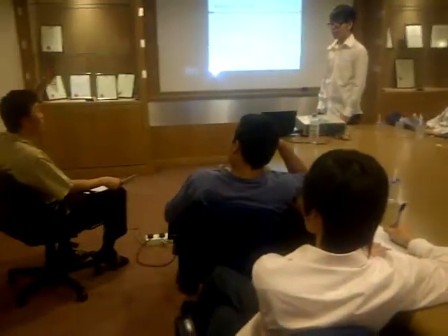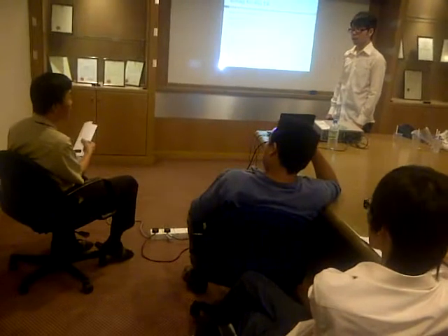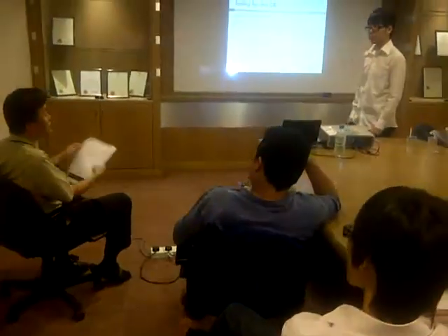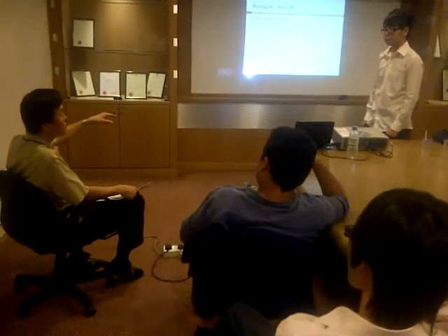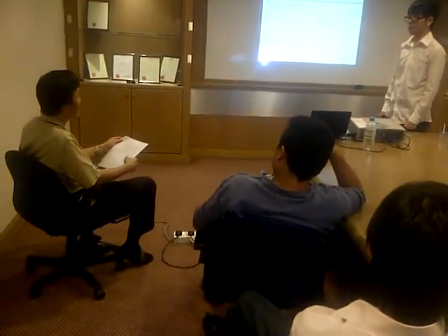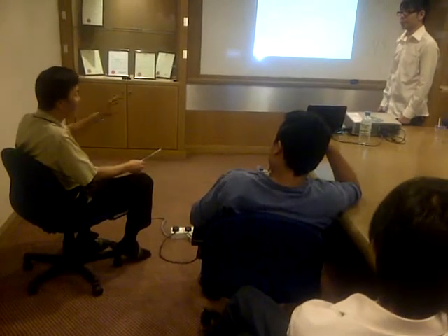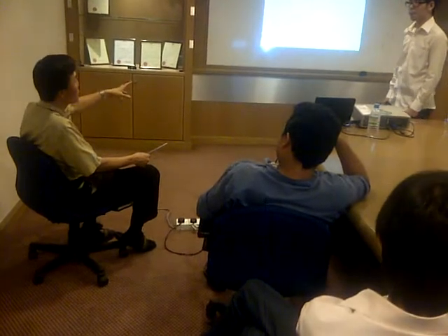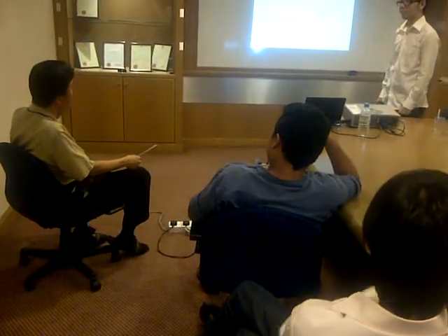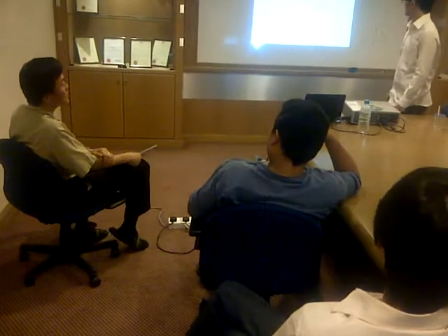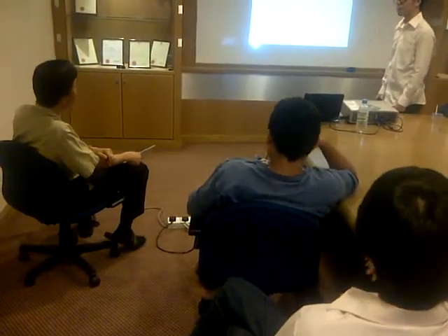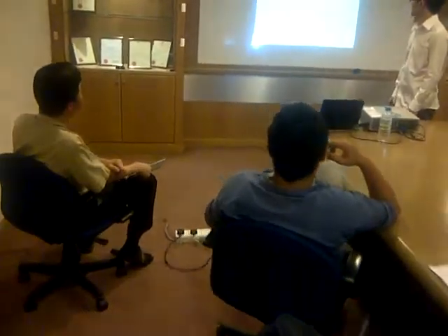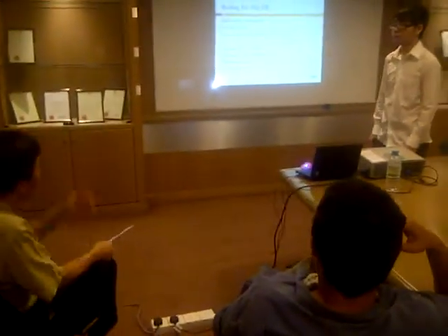You have to draft out the load profile. Just now when you draw all these things, it's called load profile. But now you have to understand the load profile, the electrical load profile for using socket outlets in the library. I believe that during the very peak time when everybody plugs into the socket outlet, it will not run as high as 70%. And when you assume 1500 watt, multiply by 77 and multiply by 0.7, 80 kilowatt is very big.